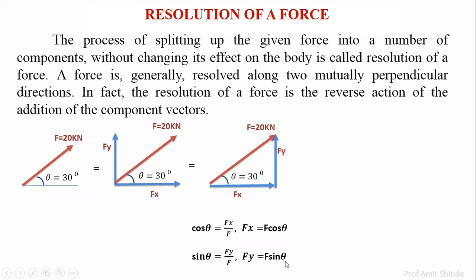It means that the resolved force components are F cos theta and F sin theta, where theta is the angle made by this force with the horizontal. Now let us calculate. Fx is equal to F cos theta.